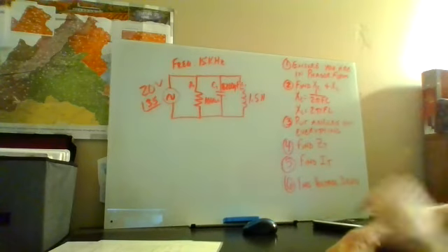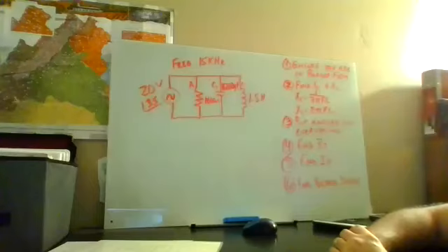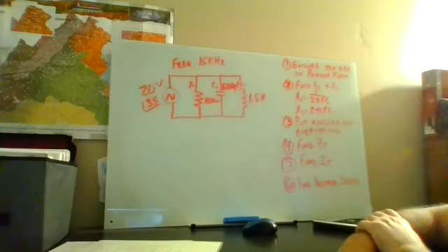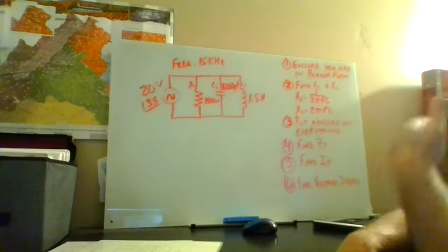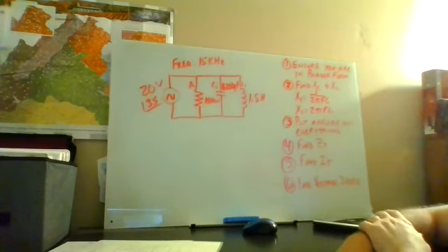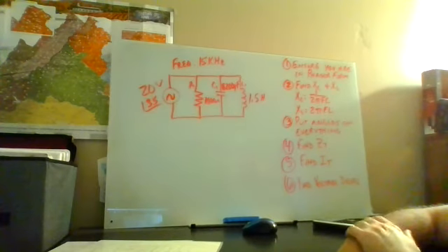So now we have an AC parallel circuit. The first thing we know is the voltage drops on these are all going to be the same because voltage is constant. But we follow the same steps. First step, ensure we are in phasor form. 20 volts angle 35, that's phasor form, so I don't have to do nothing.